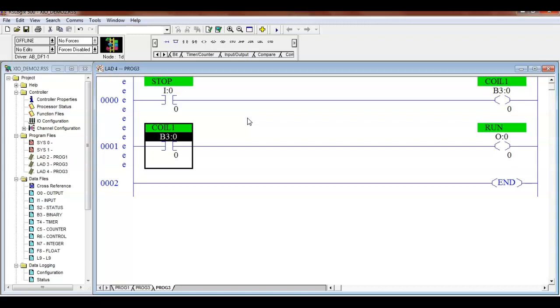So if I do relay logic, every relay has to have a relay. In large control circuits, 90% of the logic is just logic. It's just relays that are in there to do ANDs, ORs, NOTs, NANDs, and NORs. They don't run a motor. So if I can replace those inside a PLC program with what we call an internal coil, I've just saved a lot. So let's say I've got 100 relays out there, and 90 of them are doing control, and only 10 of them are running motors.